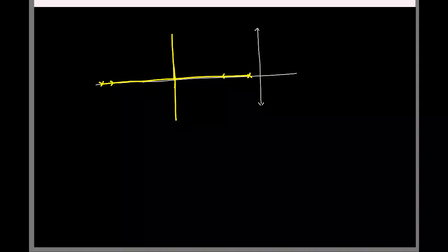So now we have this entire real axis to play with, right? What do you think might be a reasonable place for you to position the closed loop poles? Where would you want them to lie? I mean, they can basically lie here, or they can lie here, or they can sit on top of each other. On top of each other? Why? Maximum gain. Why is it maximum gain?